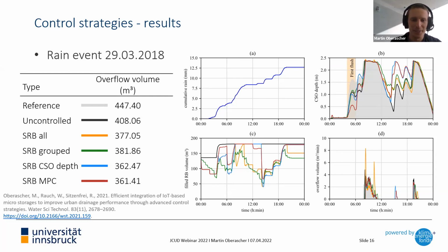And for malfunctions, yes, it's the case with the CSO structure. It would be similar, because when we don't coordinate our control strategy with the overall system states, then we create an artificial runoff wave, which could also lead to floodings. But our focus in this work, and also because it's a model-based approach, was more on CSO performance. But of course, when you go into reality, it would be important to avoid this situation, or to have some strategies so that these events don't happen.